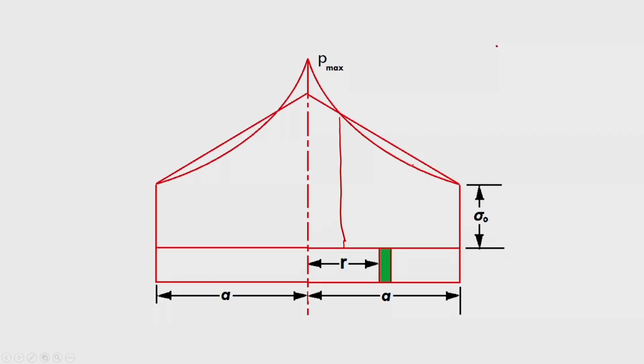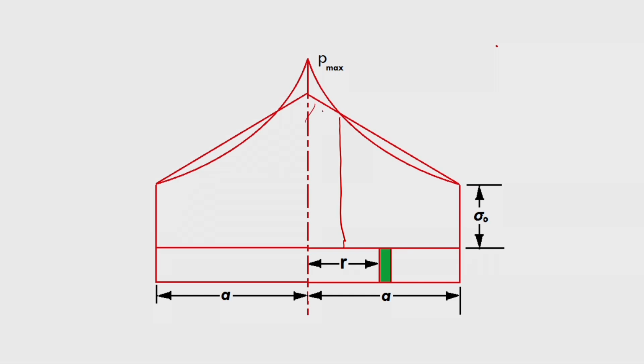When the stress reaches there, the metal will start sliding from that area. So in real application, when the deformation is there, this part from the center is the sticking condition, and here it is the sliding condition.